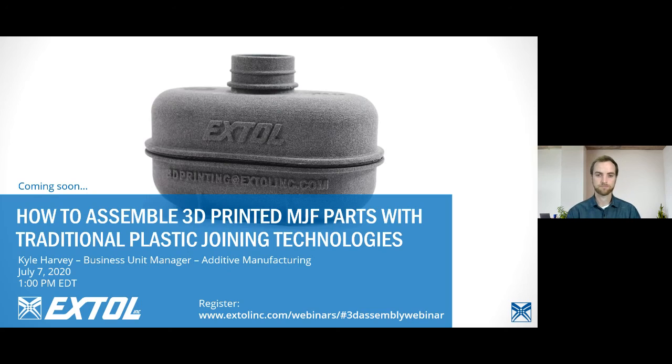All right. Do you see a dimensional change in the soft touch caps after the AMT smoothing? So once you vapor polish, do the dimensions change? Yeah. If you've got further questions on that, feel free to reach out to me. I've got a white paper that I can share with you. But the overall dimensions of the part after the AMT process are changed minimally. It's basically just taking the hills and valleys of the surface and averaging those out with the smoothing process. And a lot of that is in the recipe of the process itself.